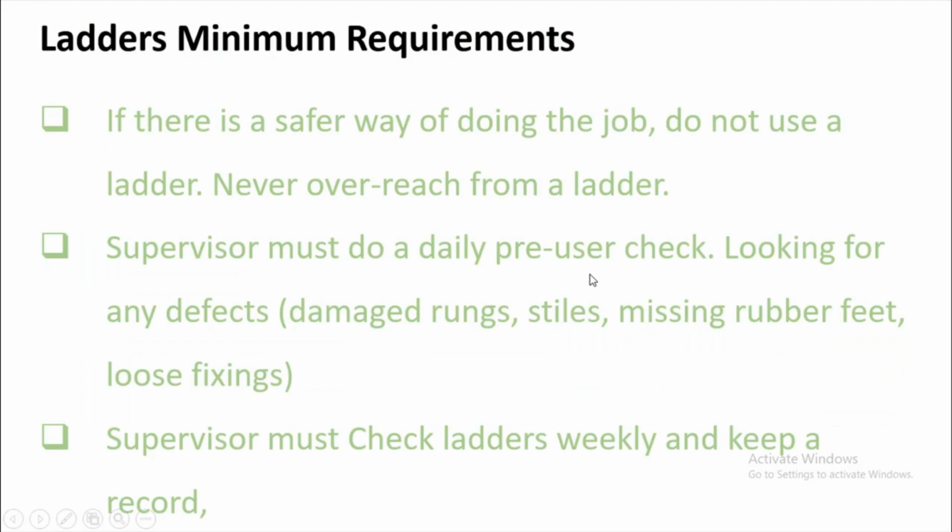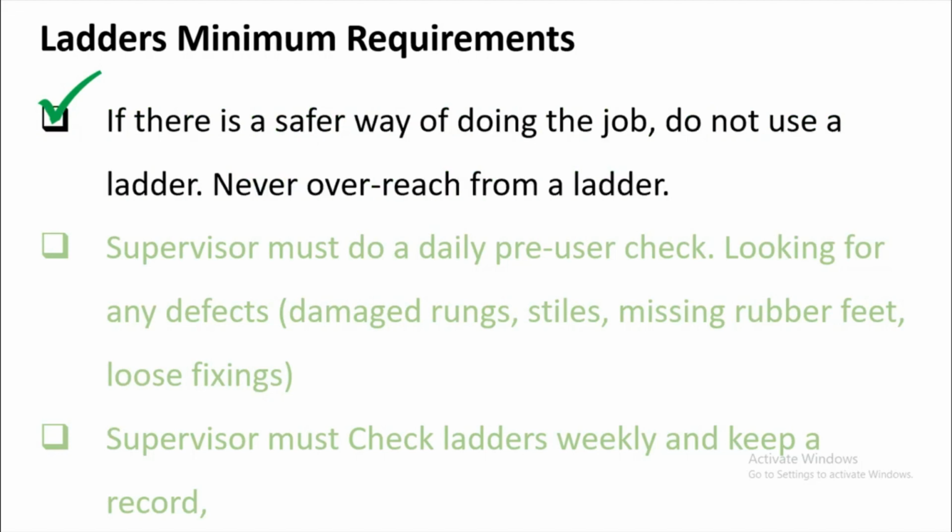Ladder minimum requirements. If there is a safer way of doing the job, do not use a ladder. Never overreach from a ladder. If you can provide scaffolding for the job, better use the scaffolding rather than the ladder. And never overreach from the ladder, because the ladder may slip because of the loss of balance, and then you will fall from the ladder.